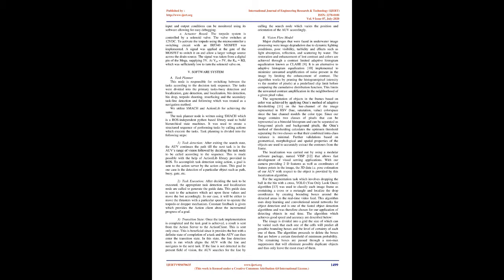UBEC, which has built-in filter capacitors on the input and output, is used to supply constant 5V to Arduino Mega, whereas to power the high-torque servo motors LM2596 is used.